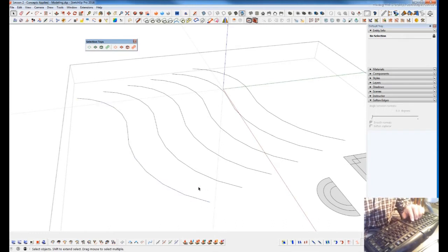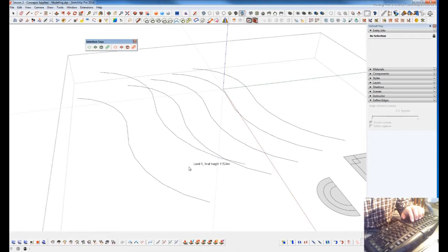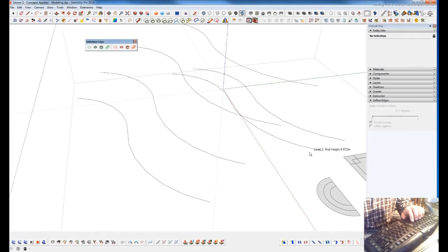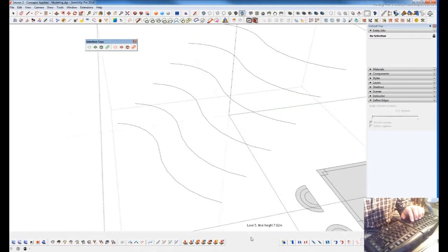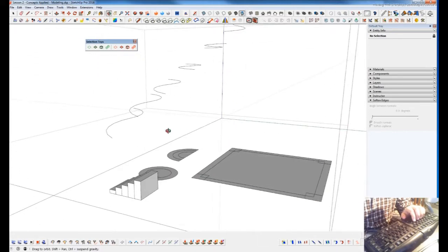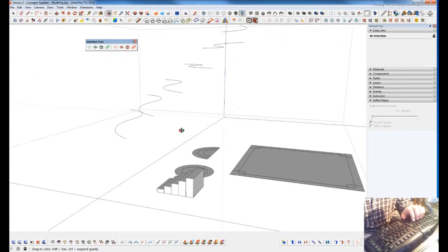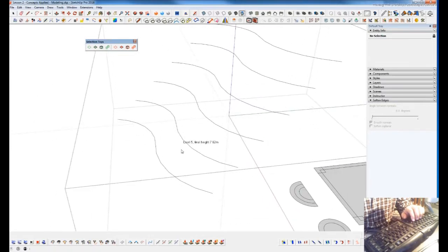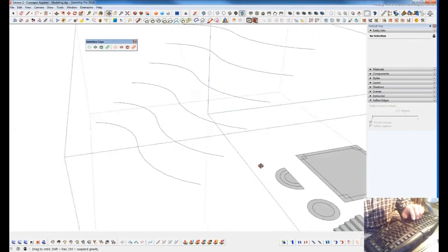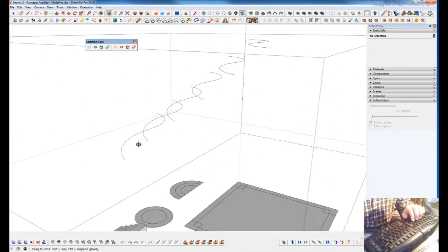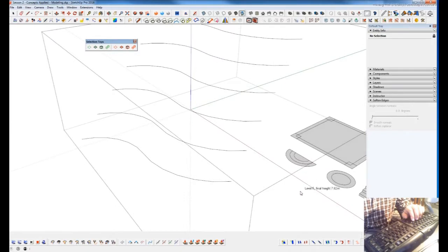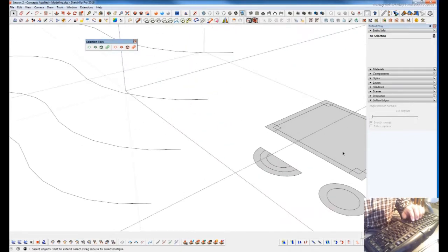When we get into contours, you usually have, let's say these are 5-foot separations of contour, and I would use my step extrude. I would type 60 enter, and now let's say the first one's set where I need it. I can click here, click here, click here, click here, and click here, and I've just stepped these contours up to where they need to be without manually having to move them with my move tool. Now, if that didn't blow your mind, I don't know what will. And I'm sure you can really start to see the power of this tool.